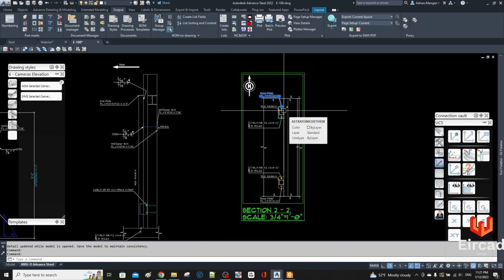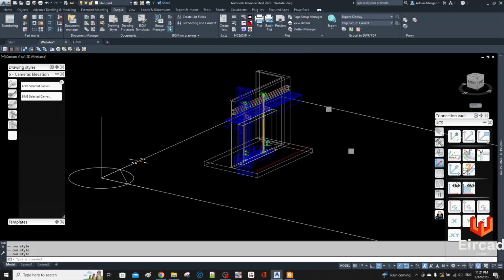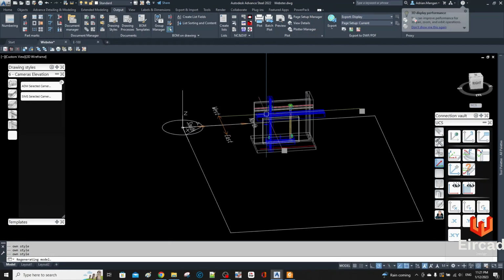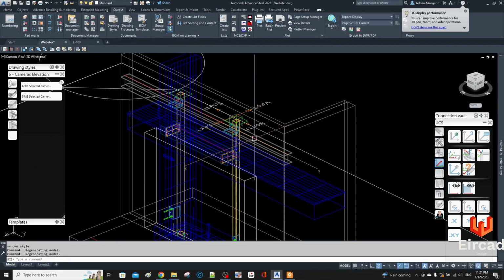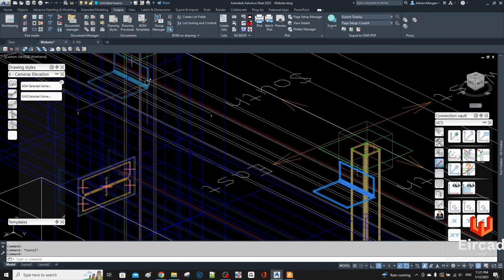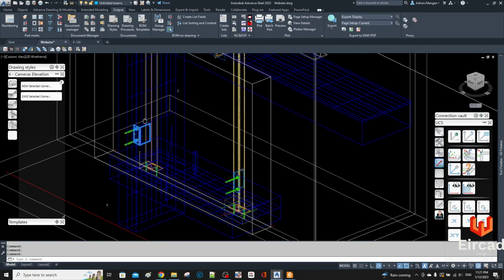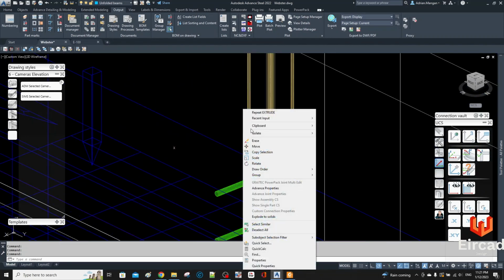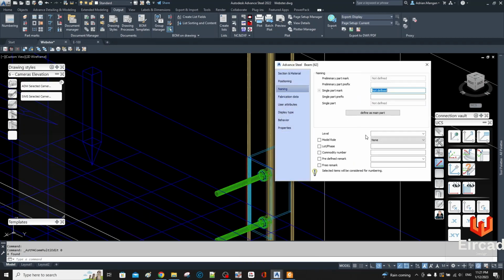After that, I suppose you want to number it. I have this set up for pre-numbering, but if you want to see the way I number it, I guess. I don't really have any steel here apart from this existing steel. So what I'm going to do is select these. I don't think I gave these a model role, so let's select these. And in advanced properties, always give a model role or it'll just treat it as a beam.